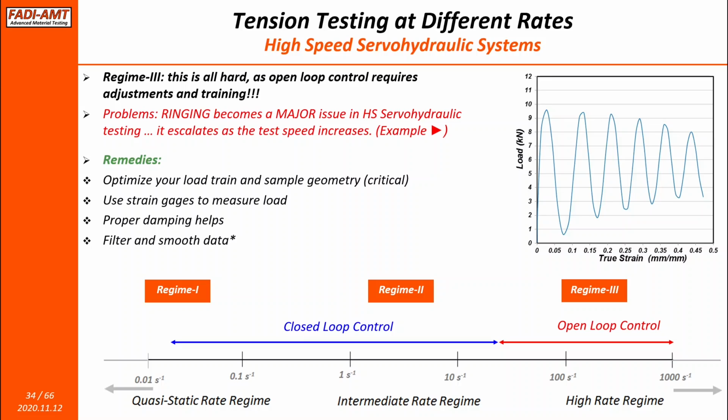So now this first item will help you improve the quality of the load signal. But then you might have to go to strain gauging. And strain gauging is just a direct solution to the problem, by basically using the sample itself as a load cell instead of using your Kistler load washer or piezoelectric load washer.